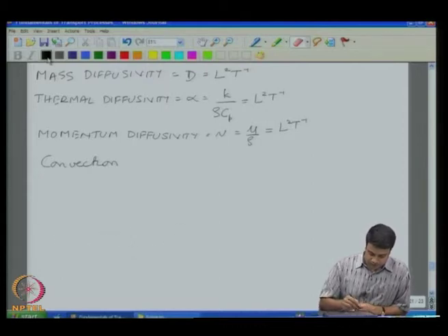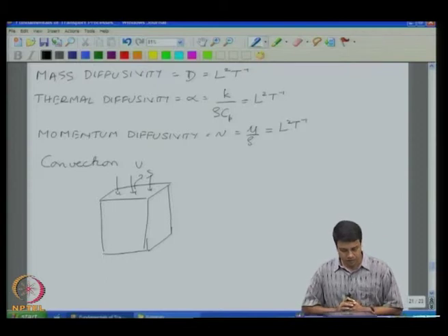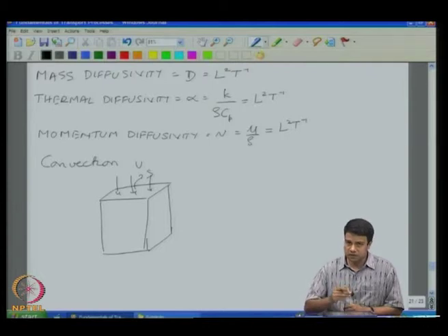So, if I have some slab of material of surface area S, and it has some velocity field here, it is moving with some velocity u, then material is transported because the material has a velocity, even though there is no difference in concentration across two different positions. Even when there is no concentration difference, there is still going to be material transported because of mean convection.